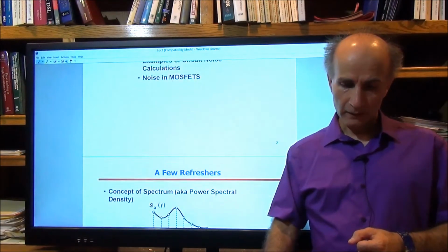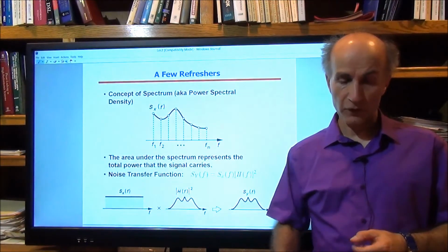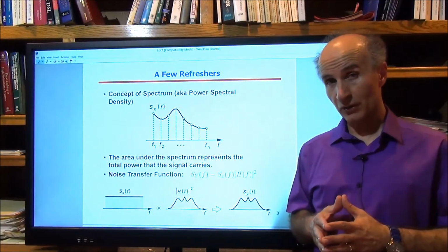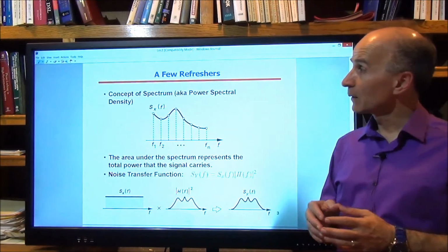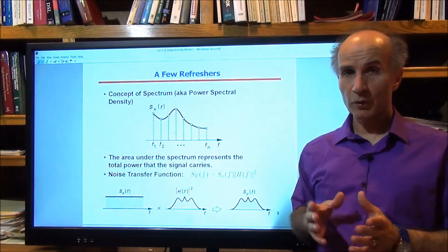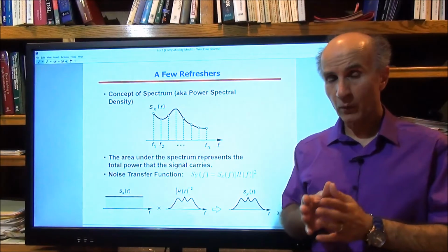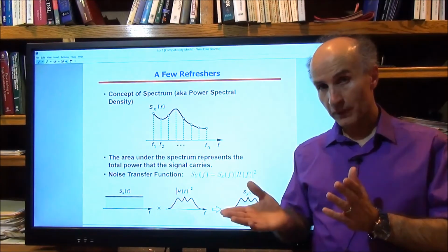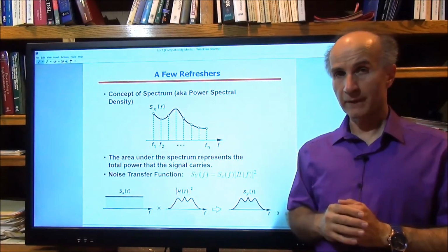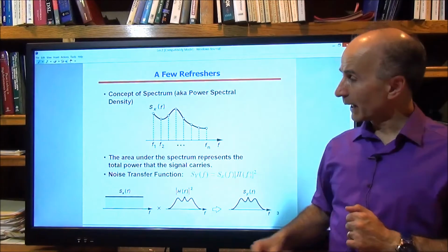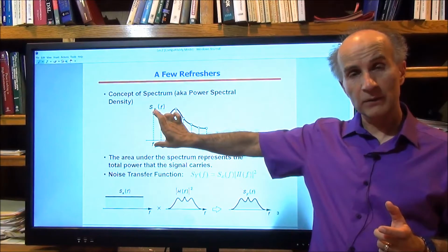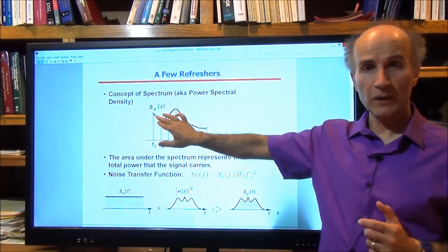Okay. But before we do that, let's just refresh our memory about a few concepts that were raised in the previous lecture. We talked about the concept of spectrum or spectral density. And we saw that the spectrum represents the average power that the signal or the noise carries in a 1 Hz bandwidth centered at a given frequency. So for example, at frequency f1, in a 1 Hz bandwidth, we have this much average power. And at frequency f2, we have this much, and so on.